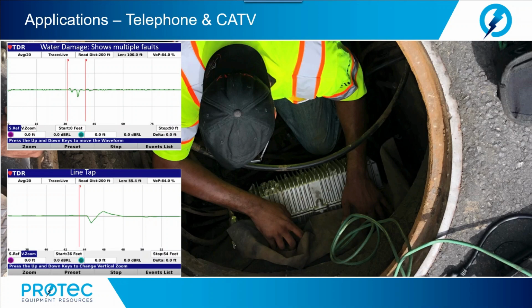For example, if the cable under test is 500 feet long and it reads 100 feet from one end and 200 feet from the other, the operator is looking at around 200 feet of overall soaked or water ingressed cable.